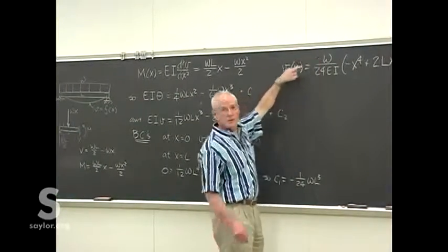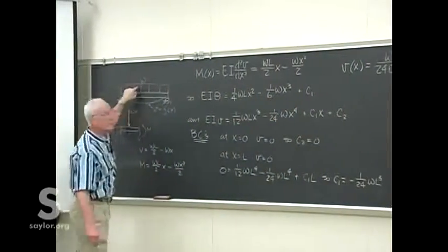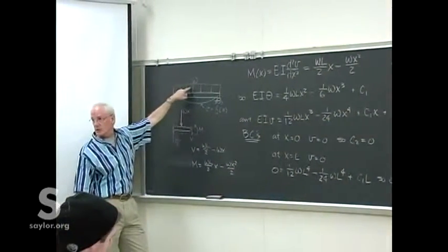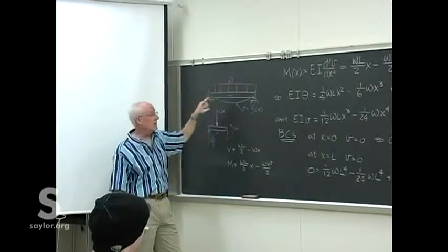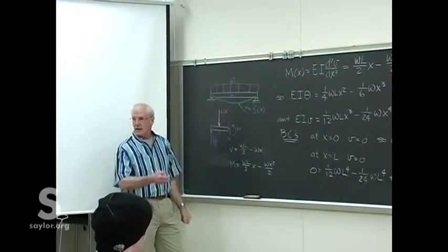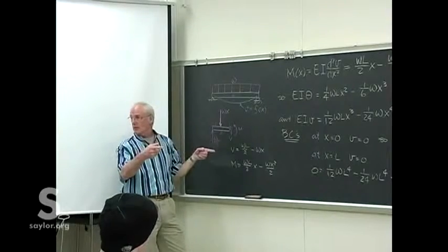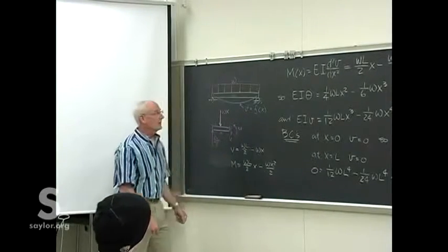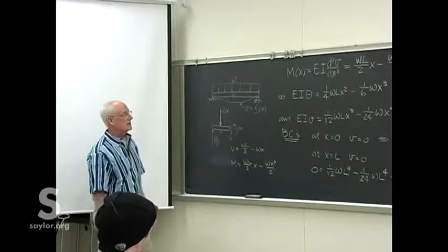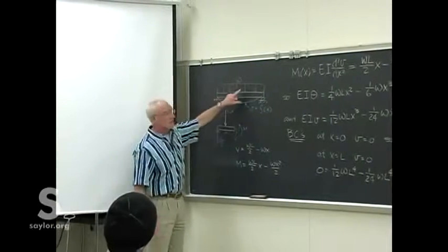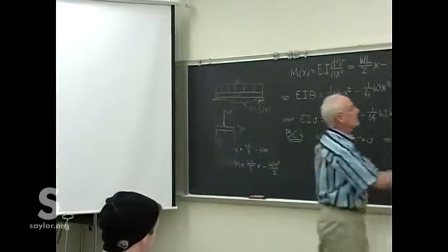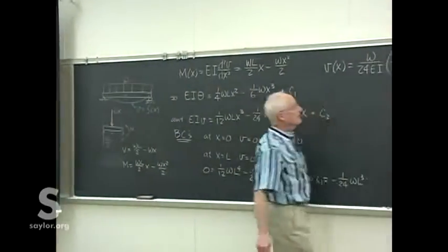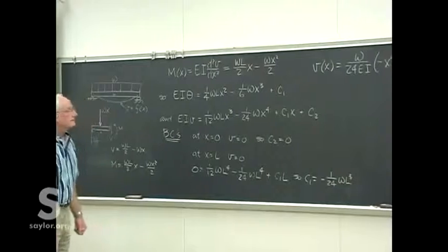Lx cubed minus L cubed x. Okay. And so now we can calculate the actual deflection. The uniformly distributed load, well, we can go into those beam tables we used the other day. Pick a beam right out of there. Remember, one of the values given there is the linear weight of the beam, right there in the beam designation. So we could figure out, unloaded just by the beam under its own weight, what its deflection will be at any point.